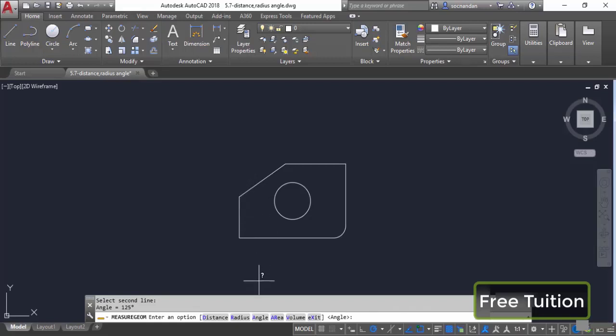Now let's repeat it once again. So I'll select this angle. Now I'll select this line and I'll click on this line. And here in this case, the included angle here will be 145 degrees. So in this way, you can find angle between other geometries as well.